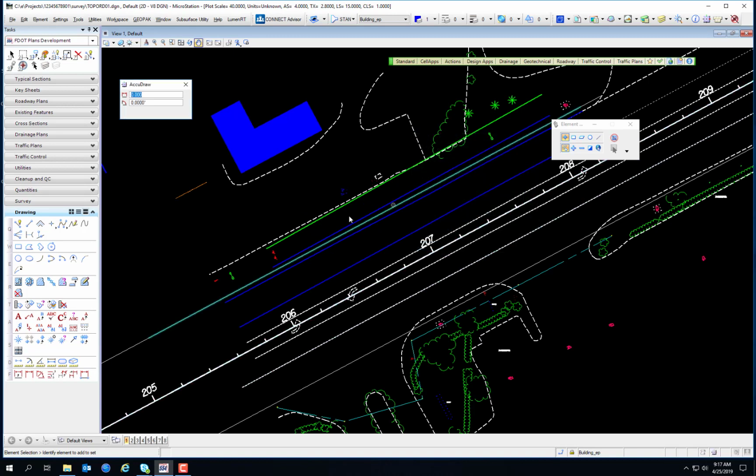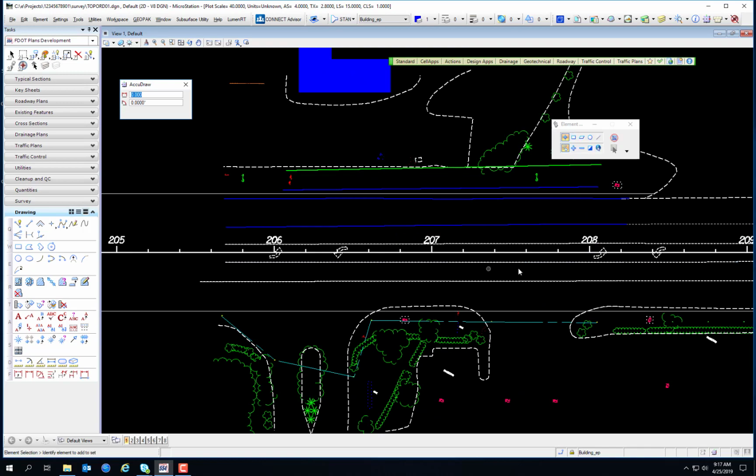As I've said before, let's go ahead and rotate this view so that it matches the screen. So I'm selecting the Rotate View tool, making sure it's set for 2 points. I snapped to the midpoint of that tick mark, and so I'm going to go ahead and just snap to the midpoint of 208. And there we go.